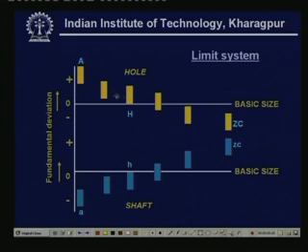I am just trying to say this is a clearance, snug, and the very tight fits. Normally, people won't be referring to this zone. It's a very rare zone where you have these types of tight fits. This is mostly where very high hammering or pressurizing only can keep two machine elements, namely a shaft and hole, in a mating condition.